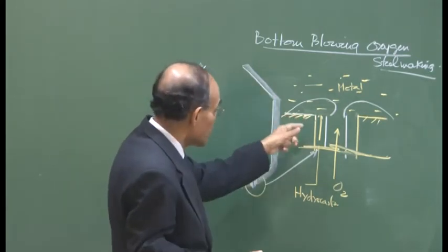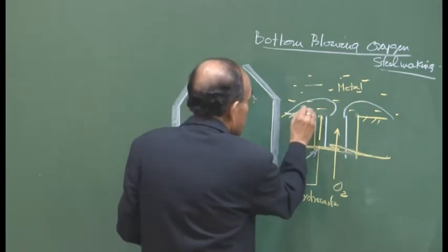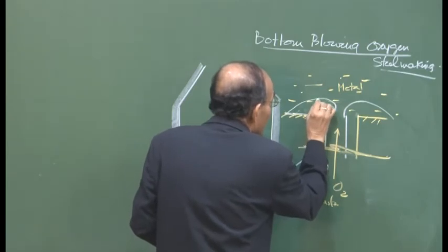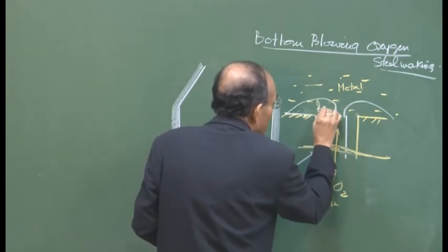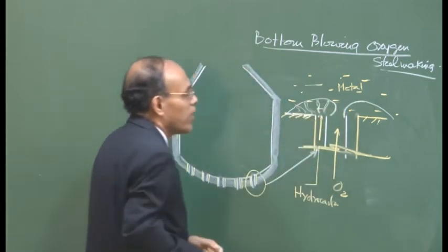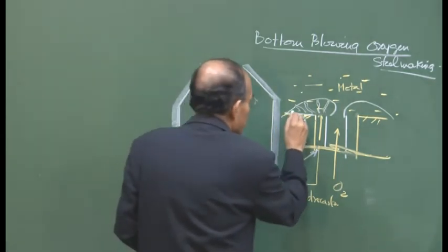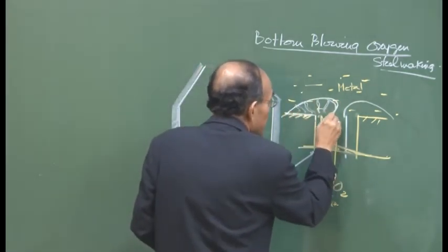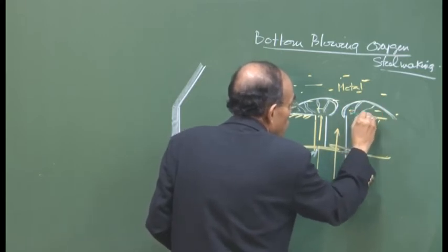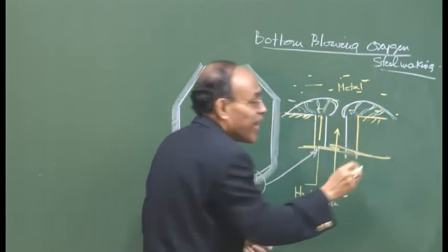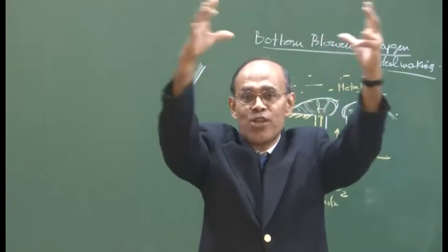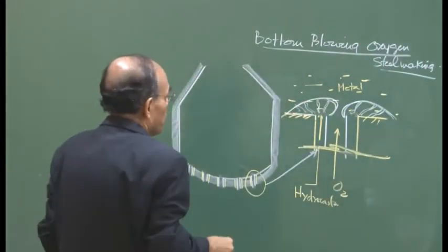Because of the low temperature, because of the cracking reactions, and because you are blowing hydrocarbon, there are also pores, there are channels, you have high pressure, through which the hydrocarbon gas will go out, and this basically gives rise to some kind of protection. So, these are passages or cracks in the deposited metal. We call it a mushroom shaped structure that grows around the